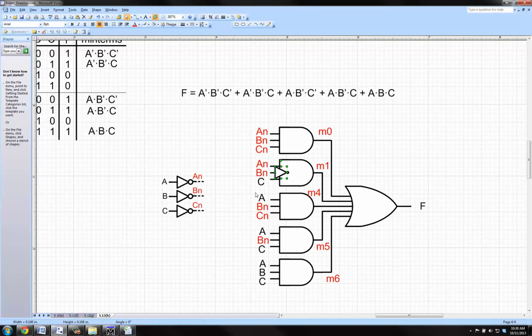So let's just put down the names of what we're going to basically design. We need to make inv1.vhd, so that's going to be one file that we need to make. And then we're going to make an and3.vhd. This naming convention is very common in VHDL: you put the logic operation followed by the number of inputs, and then we'll do an OR 5. And what you'll actually find is that a lot of the libraries and tools actually have these basic gates for you, but we don't have them, so we're going to build them ourselves.